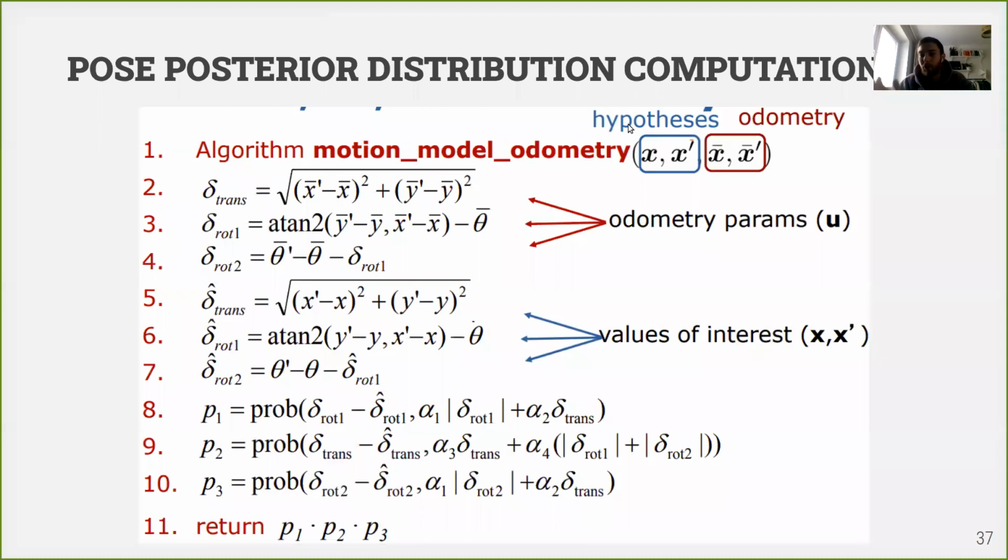If we are talking about the particle filter, and we had better, because this is a really common algorithm, hypotheses are discrete particles. Each particle is a hypothesis on the robot pose or robot state, because it can be applied not only to wheeled robots, but also, for example, to arms. An arm also has a state, represented by the angles of its joints, and we can do the same.